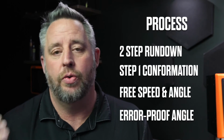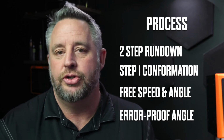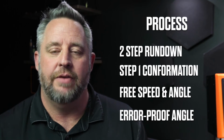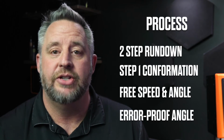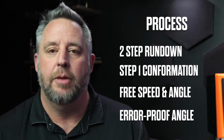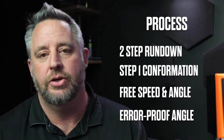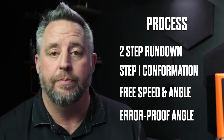The slower you go, the more accurate you can be when you come to a stop sign on how close you would be to the actual stopping area. So that is kind of the concept behind that. And then we'll also show you how we can set an error proofing angle if we did have a washer stack in there and that washer stack was not present. We would be able to see that within the rundown.